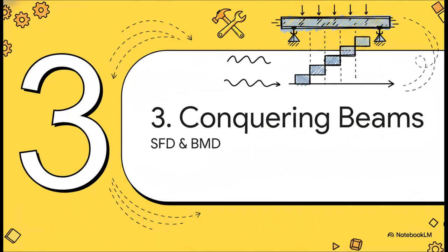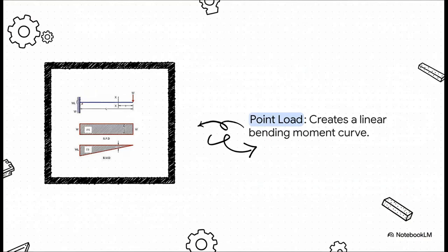Next up, Section 3, Conquering Beams, SFD and BMD. Let's start with the simplest case. Picture a cantilever beam with a concentrated point load sitting right at the free end. Notice the shape of the resulting diagrams. The shear force diagram is a simple rectangle, but look at the bending moment diagram. It's a linear, triangular curve. A point load creates a linear bending moment.